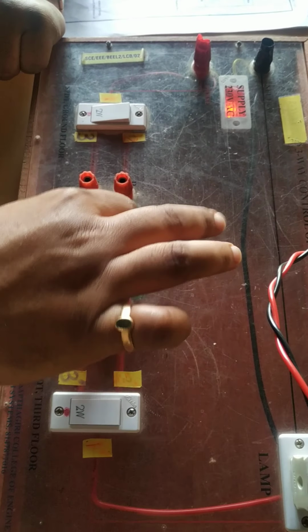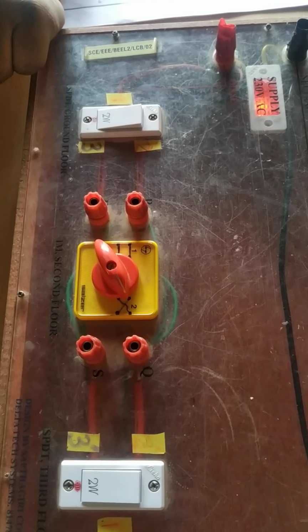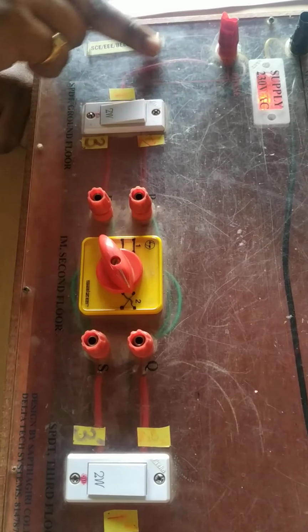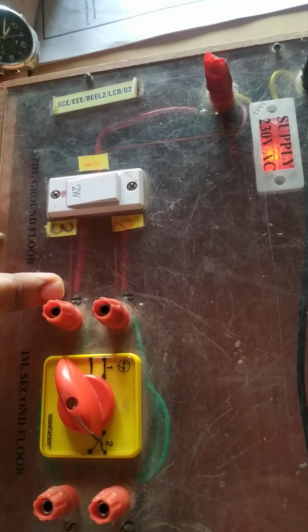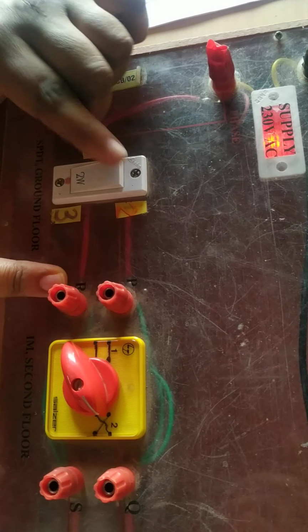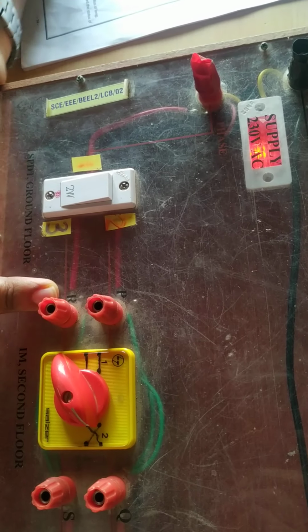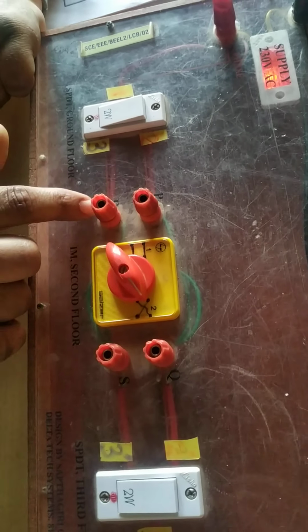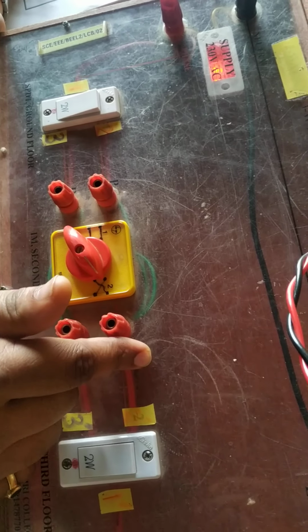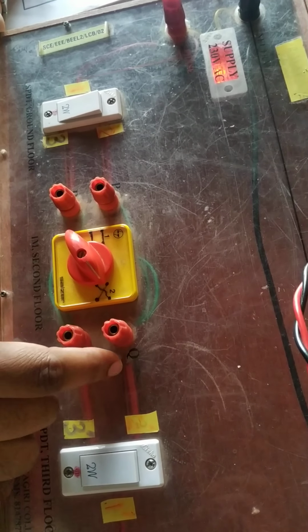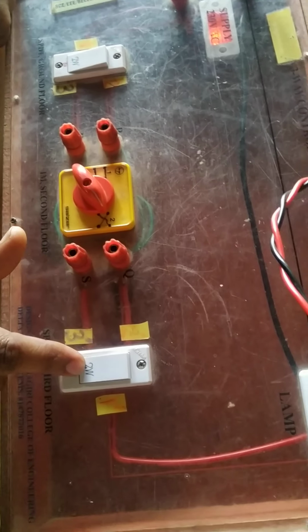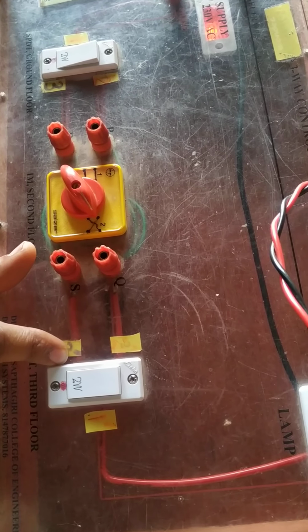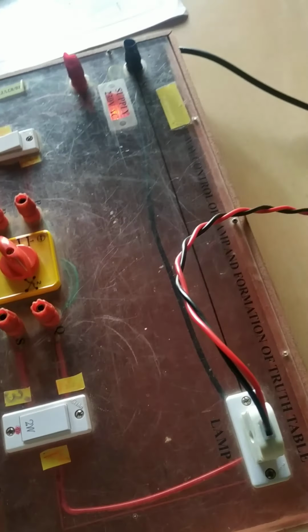Now I'll change the intermediate switch to cross connection. Now what is happening? The supply comes and hits the 1 dash terminal. From the 1 dash terminal it is coming to R because switch A is at 1 dash terminal now. So it is coming to R. Since it is cross connection, from R to Q is where the current is flowing. From R to Q it is coming, from Q to 2 position it is going, but switch B is at 2 dash terminal, 2 dash position. Therefore the lamp is not turned on.